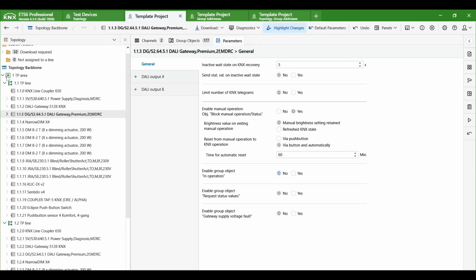And finally, we're looking at global scenes, also known as KNX scenes. The difference with these scenes is they're incredibly powerful, because the memory of the scene is saved throughout all the devices, and to call a scene over the network is only one telegram to tell all those devices to go to that scene, to do what they've got to do. And so the difference is we're not relying on a server, we're not relying on a device if it breaks, we're relying on a whole lot of things. You've got all inputs and stuff.